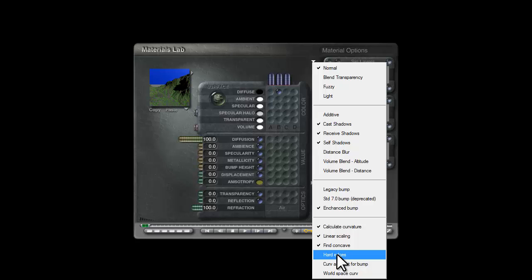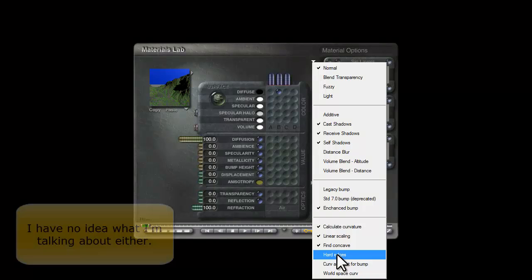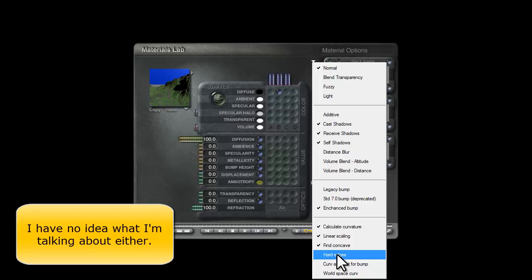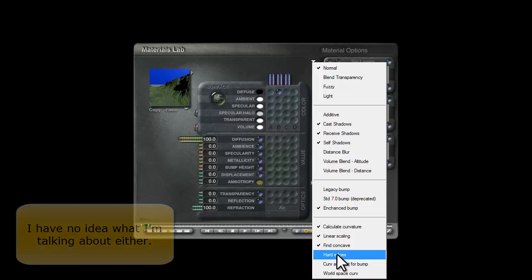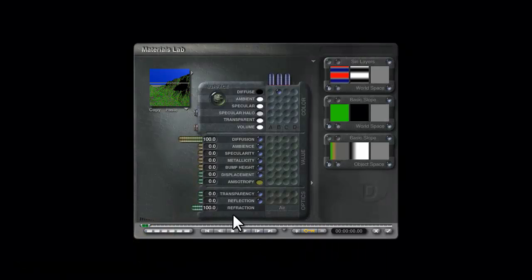But in going into a corner or out to a pointy out edge, you have to decide whether the lead-in points, because they only have an X and Y inward curve, count as being on the curve or not. Or if you don't have hard edges, you just have the points because they've got an X, Y. It's getting really complicated. Anyway, just choose hard edges for terrains. That's probably the best answer.